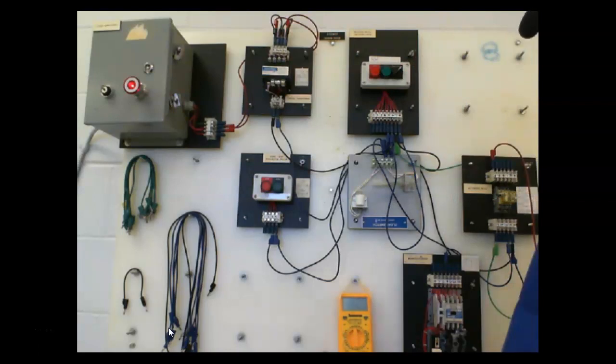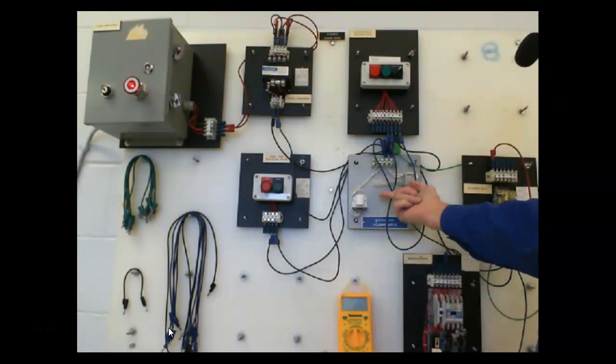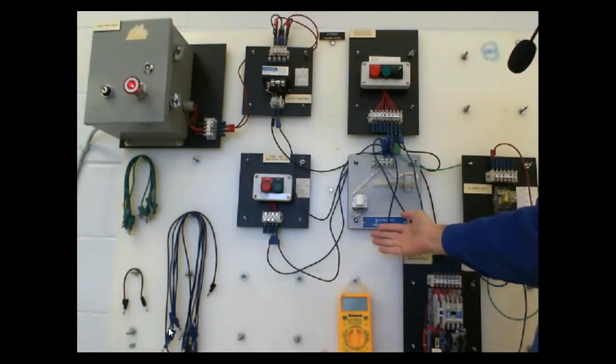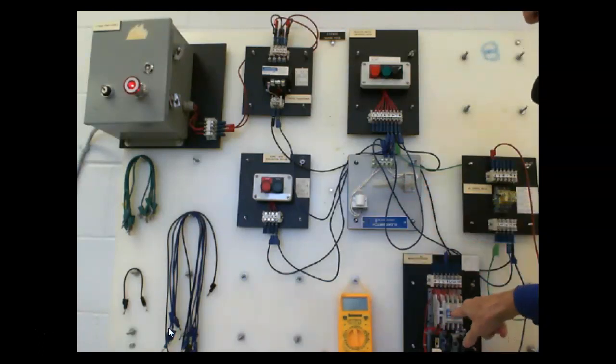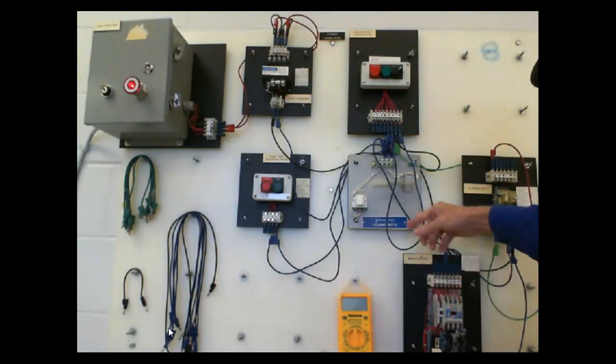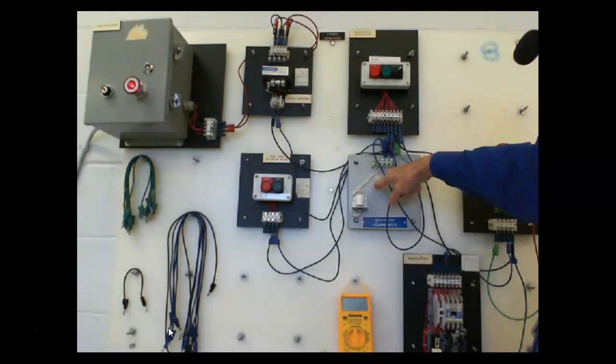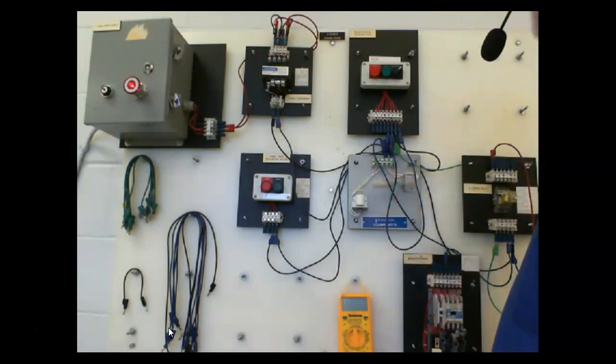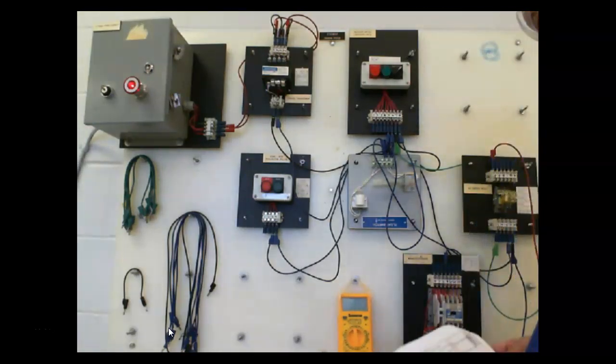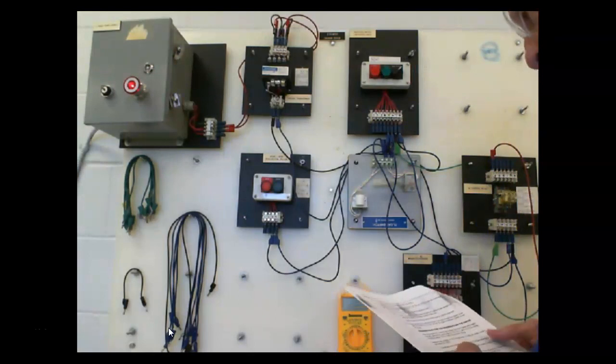If I put it in the auto position, then now we've moved over to the level. So my pump is running, right? The relay's energized. Y'all can't see it, but I can see the relay's energized. This is the motor starter. When the level gets up too high, we turn the pump off. So this is called a pump control, and it's also called a charging control. It's got two names. Are we okay? So we should have two answers here. We should have one for... no, we should have three.